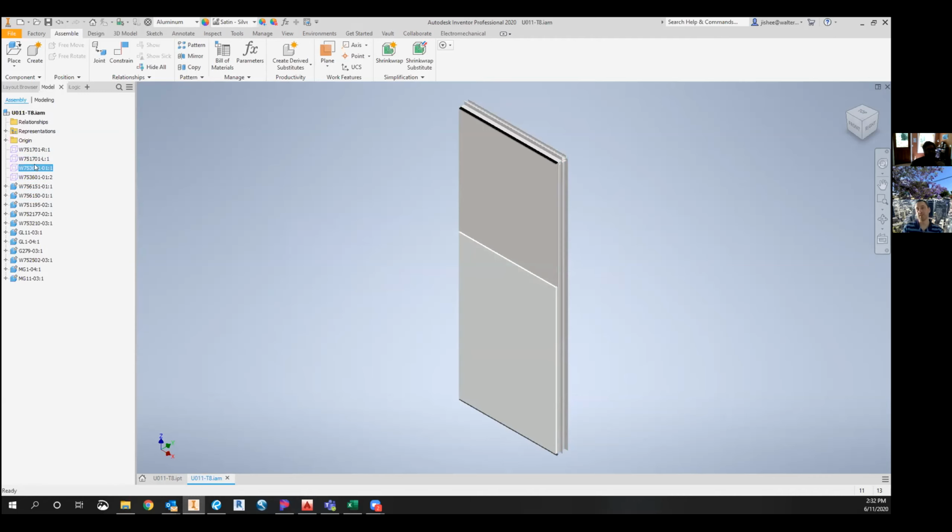So we don't want to take the time to model it. We have kind of master part files for those, part drawings for those that we're not going to create and model every single time. They're just the same from job to job. So those will just reside in the template. But this way they will show up in the bill of materials and be counted and all of that.